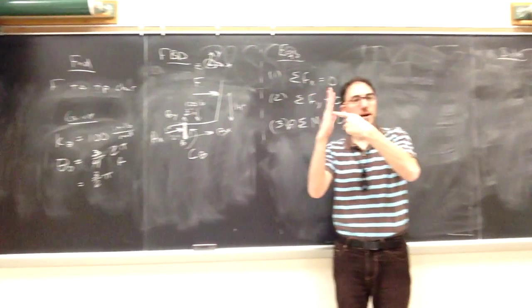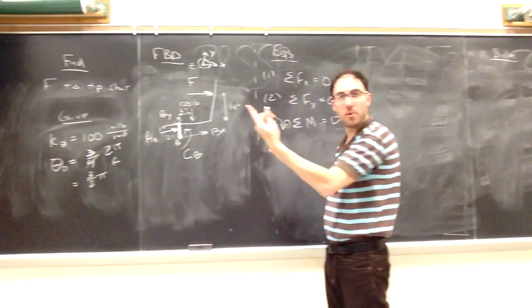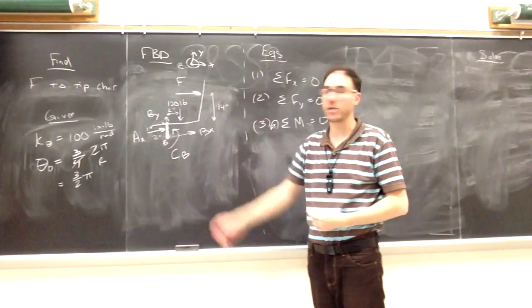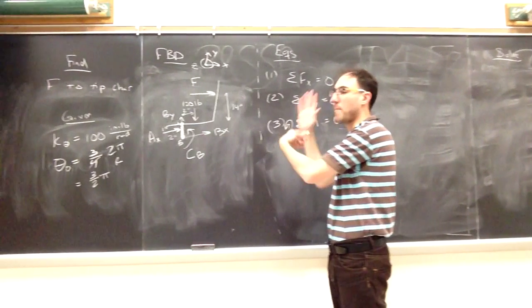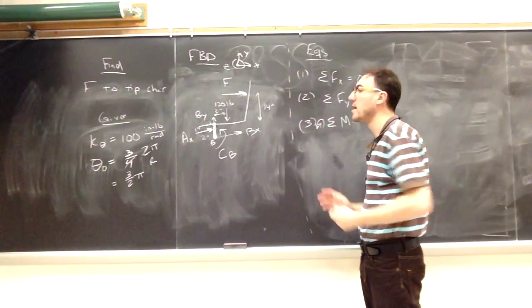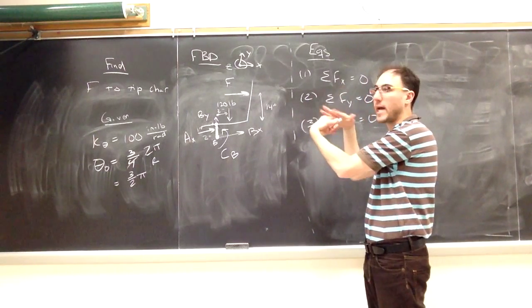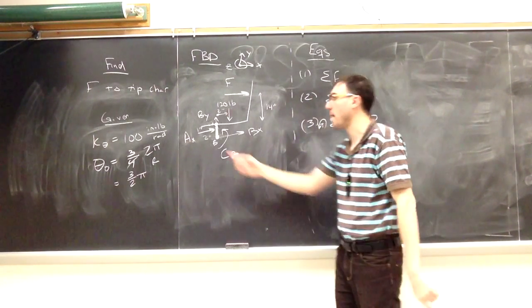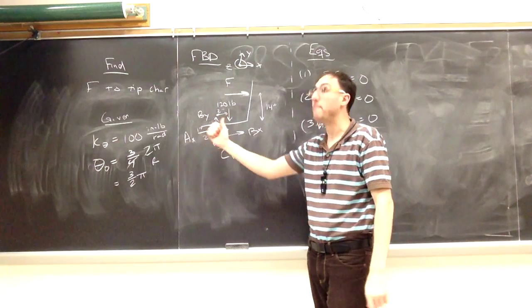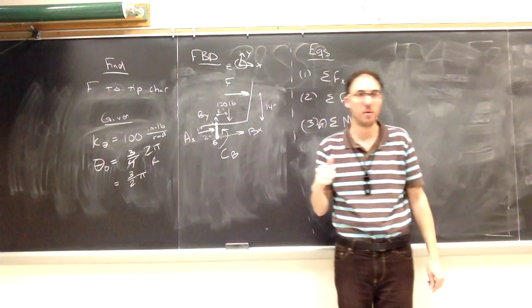Right, so that stopper prevents it from moving to the left. We're assuming there's no friction until we get to the friction chapter later, so that stopper does not prevent it from moving up and down. And the stopper does allow it to rotate with respect to the stopper, so the stopper only exerts what must be a rightward force on the post.